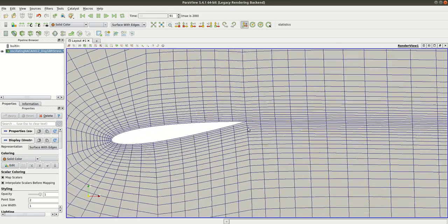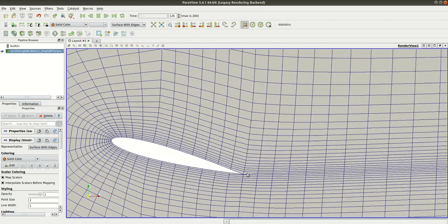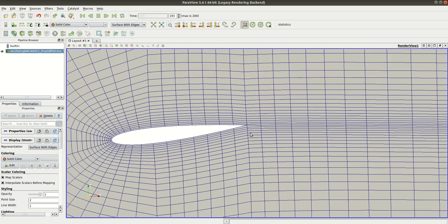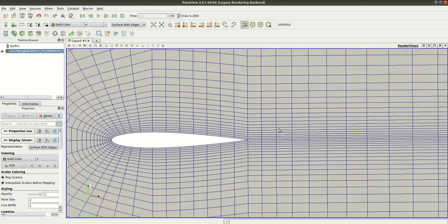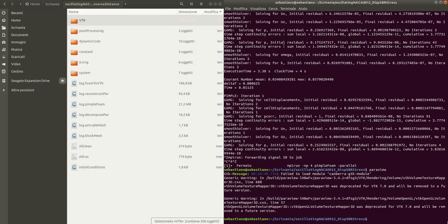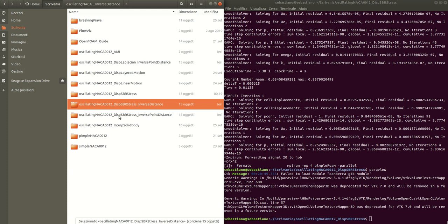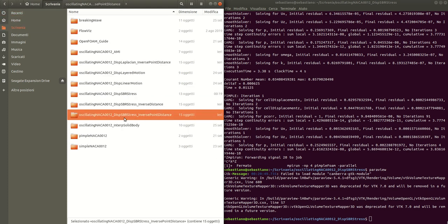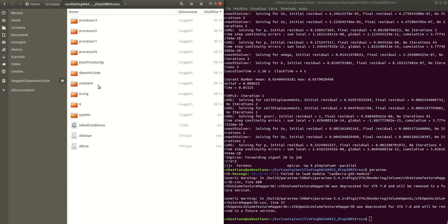In this regard, the solver that I explained in my last tutorial is better from this point of view, because you can fix a zone around the profile where the points are moving rigidly. But when we use the finite volume motion solver, we have the possibility to use manipulators, and we have also the possibility to change the computation of the diffusivity. For instance, this is a trick that I always use.